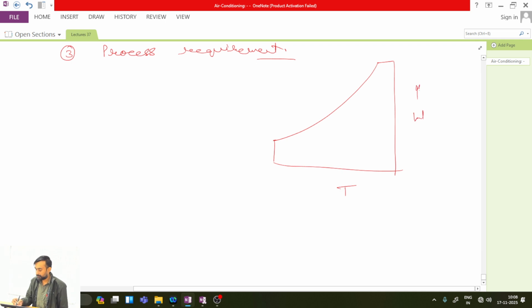So if the RSHF line becomes steep, what happens? This is my point 1. Under these scenarios, 2-3 issues can happen. One issue could be that the RSHF line will become so steep, because we have more amount of latent heat.